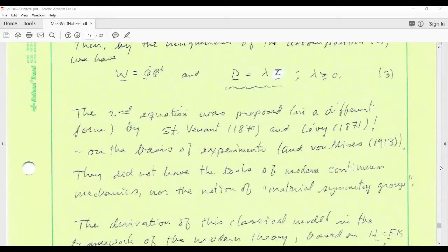To recap where we were last time, we derived equation 3 here. Can everyone see that? Yeah? Okay. We derived equation 3 systematically from our theory of finite deformation elastic plastic materials under the assumption of isotropy for the constitutive functions, which depend on elastic strain or equivalently on the stress S. And then we invoked the idealization of a rigid plastic material. That means we assume that the elastic strain is so small compared to the overall strain that we can safely neglect it as a useful idealization, which means the elastic deformation H is a rotation field. And that led us systematically to equation 3.